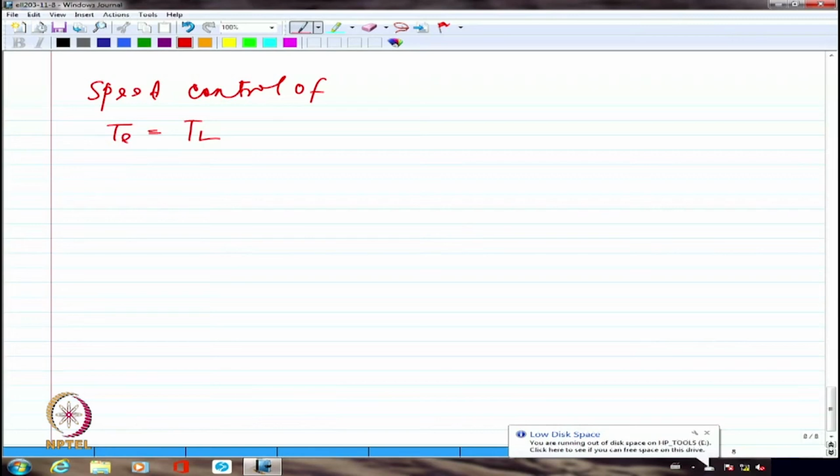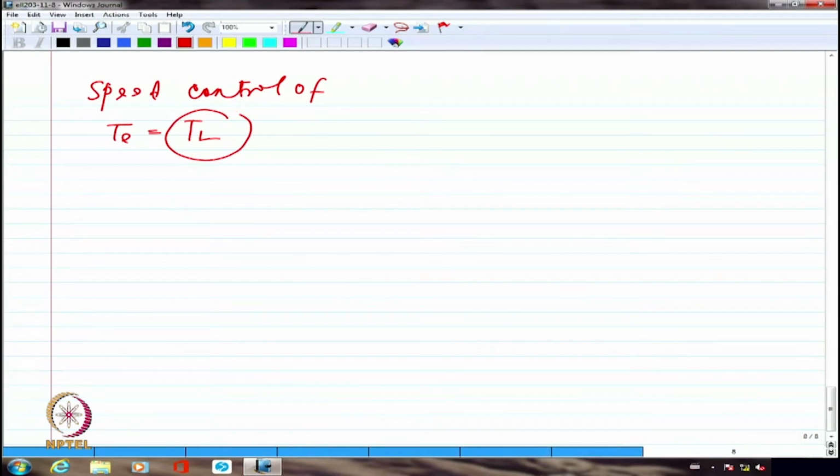So you have load torque as a function of speed. It can be a function of speed square, or it can be a constant value. It can be either way. So we are essentially looking at the load torque as some value which depends upon whatever your load mechanism is. What you have to understand is, just like how you write F equal to ma in the linear system, I should be able to write J d omega by dt equal to whatever is the torque available for accelerating it. The torque available for accelerating it will be what is generated as electromagnetic torque by my motor minus the load torque demand.